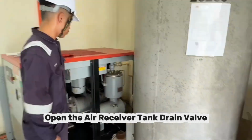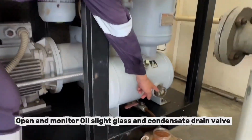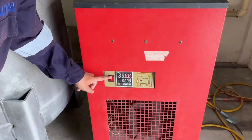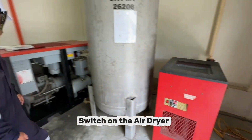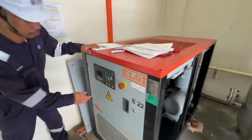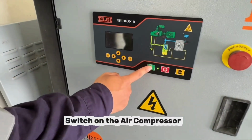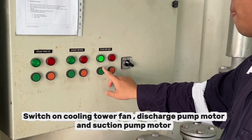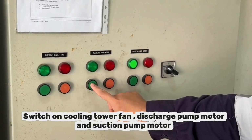Open the air receiver tank drain valve. Open and monitor the oil sight glass and condensate drain valve. Switch on the air dryer. Switch on the air compressor. Switch on the cooling tower fan, discharge pump motor, and suction pump motor.